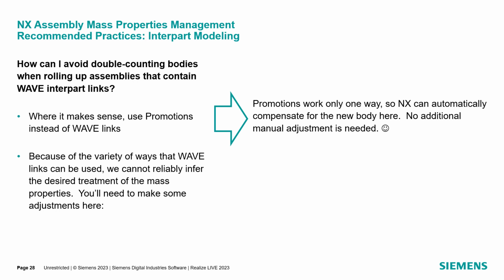It might be used for things like cross-drilling, match drilling at an assembly level, or even for things like castings, where we may have an original part. We link it upward in a structure and then do some subsequent material removal, for instance, squaring off faces or drilling holes or things like that, kind of one level higher.